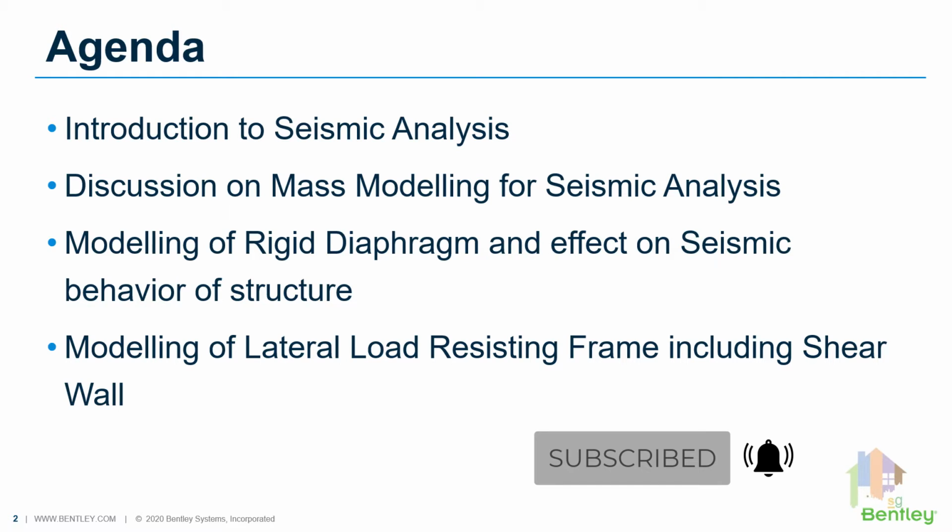I will discuss the different international codes available for static seismic analysis in STAAD, a brief discussion on the newly implemented IBC 2018 code, and the different options and parameters that need to be specified for the static seismic analysis. Then I will cover mass and stiffness modeling, how to define the seismic mass more effectively for both static and dynamic analysis, different types of diaphragms and their effects on seismic behavior, and finally, how to model the diaphragms and shear walls easily using the advanced options available in STAAD.Pro CONNECT Edition.